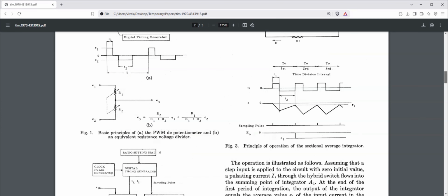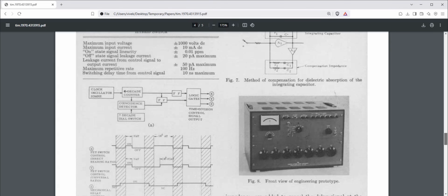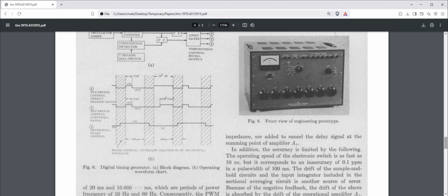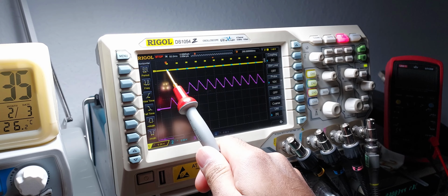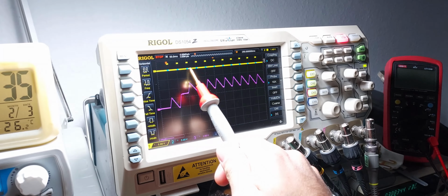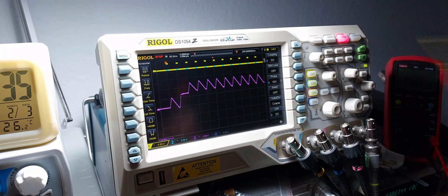The next control scheme was inspired by the original paper. In the waveforms in the simplified diagram of figure 3, the PWM is run continuously and the sample pulse is very narrow. However, figure 6 presents a more plausible scheme, with each reference being turned on individually, with a blanking period in between. What I came up with was slightly harder to implement in code, but thanks to the flexibility of the PWM peripheral, I managed to make it work.